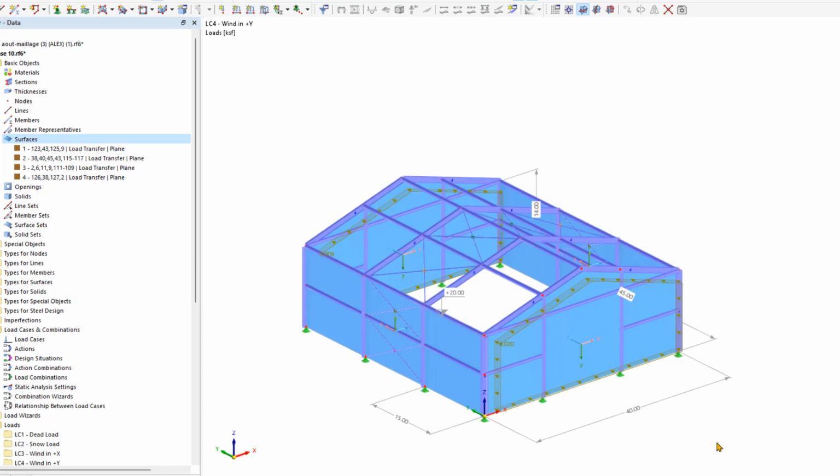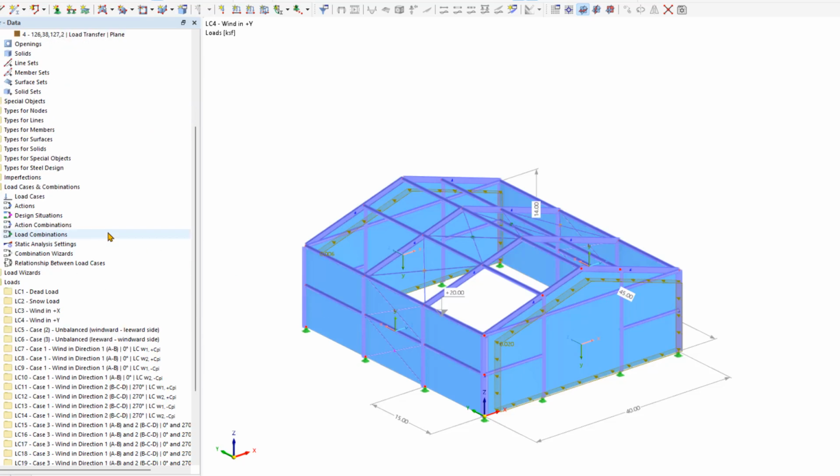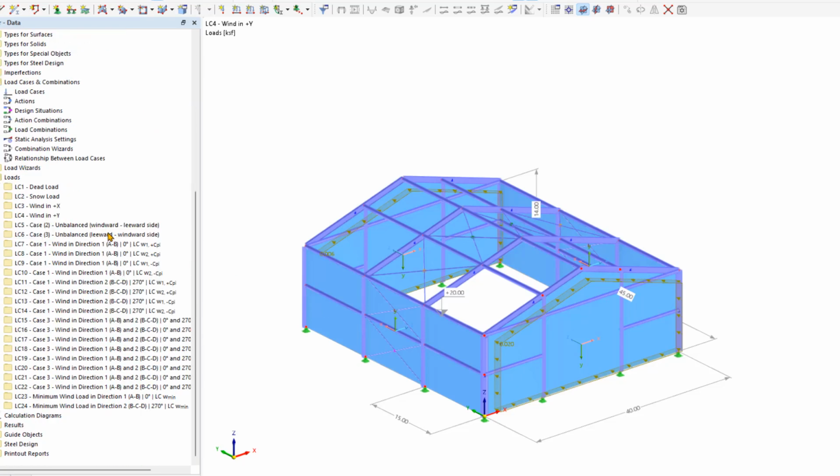These loads act together from the same directions. We've also assumed that we cannot automatically generate these wind loads on the vertical walls using the load wizard. To consider this interaction, we select the lateral wind loads in the navigator and add them by right-clicking on the respective automatically generated wind loads of the roof.